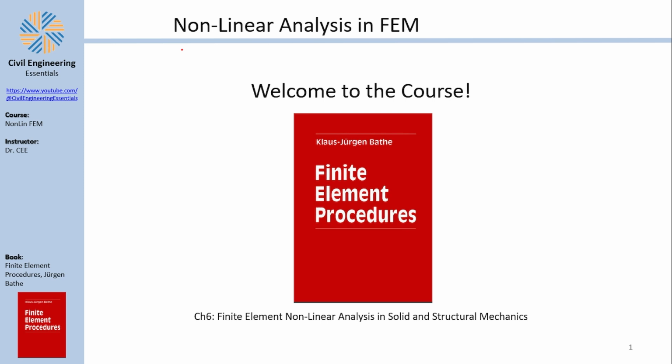If you're, for example, designing for the ACI code or the Eurocode or any usually well-known code, you would realize that you are usually dealing with a section at the ultimate phase, basically when the material is starting to crack or the steel starts to yield. This is the ultimate limit state, and it is usually done in near failure conditions, meaning that our material would not behave linearly in that case, but nonlinearly.